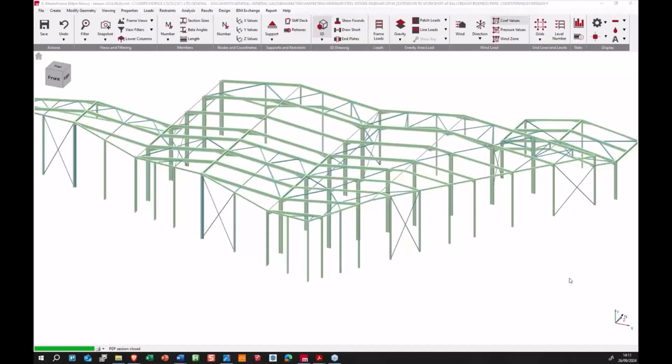So you're not really looking at the sway mode load case there. And that actually recommends you do step back to the British method of assessing the elastic critical load factor if you are doing it by the deflection method. So our latest MasterSeries 2024, the up and coming patch that's going to be released, will include some work on that and a bit more control over which loading cases get used for the assessment of elastic critical load factor as well. But we'll release a bit more information on that through our blog post channel to discuss that in a bit more detail. Really interesting topic area that actually.